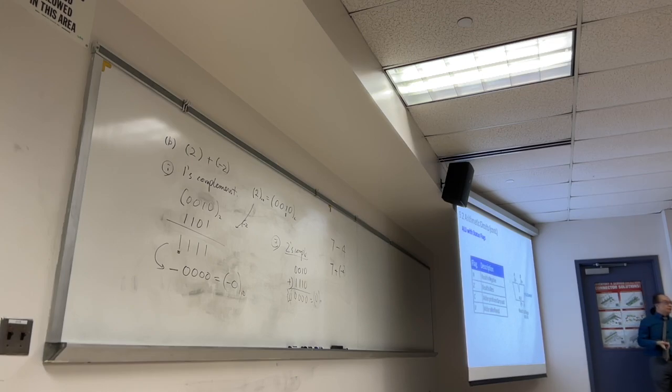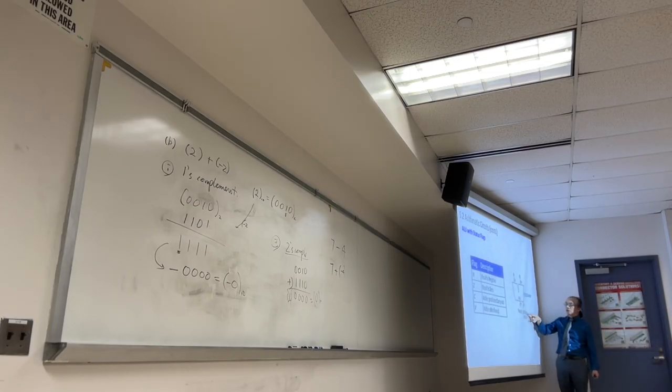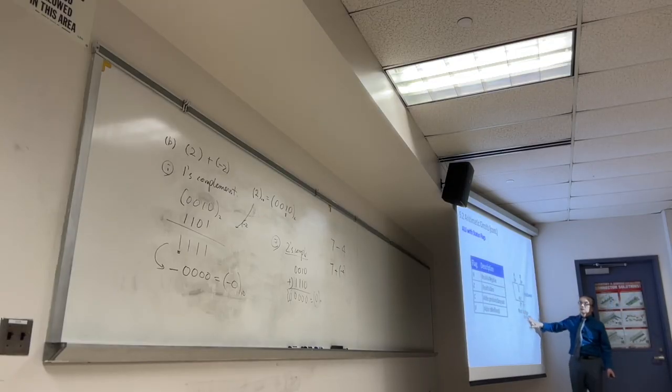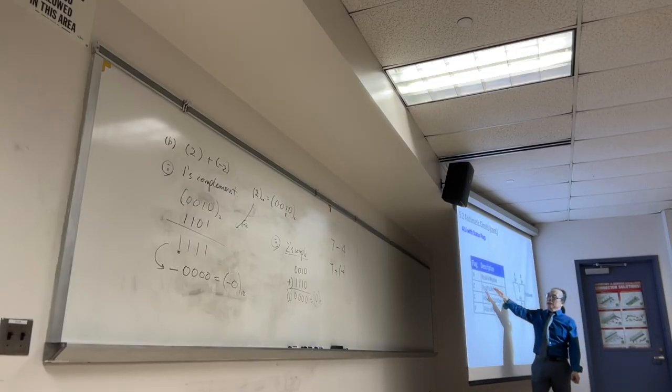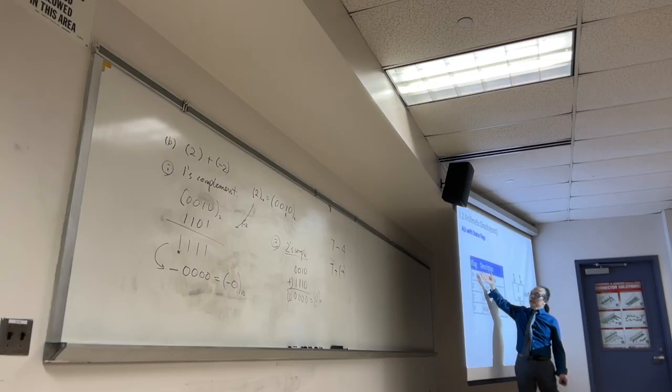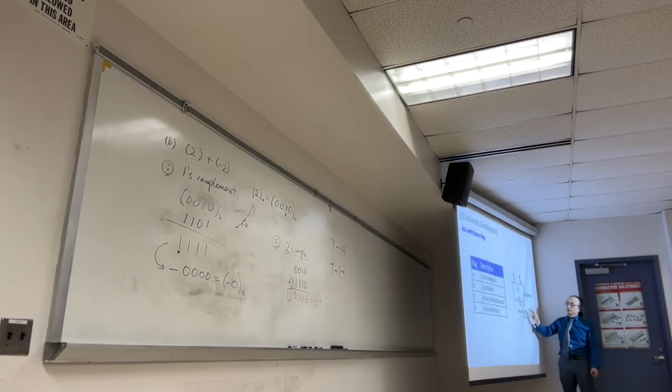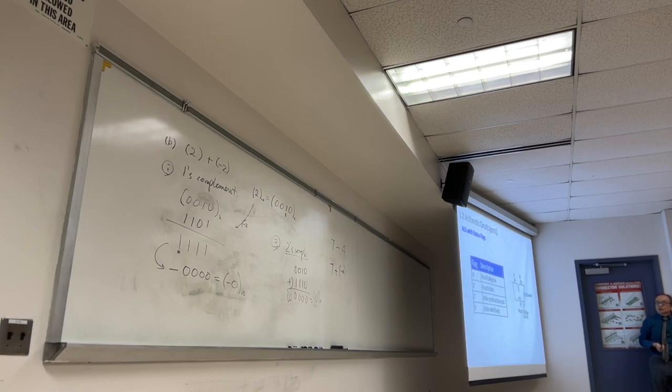Okay, flags, that's the keyword. Flags. We're going to get flags from the ALU. So when we feed in two binary numbers, we should be able to get flags, the 4-bit equivalent to NZCV. Based on this flag, we know whether those two numbers are the same. If they are the same, we're going to have Z equal to 1, right?